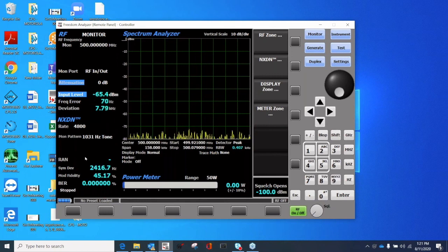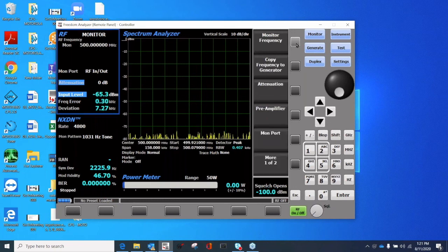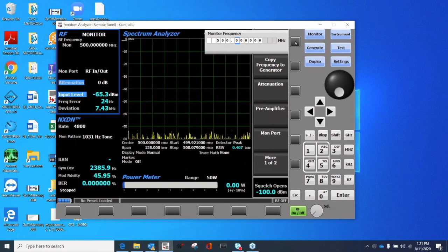Suppose you receive a radio from the field and want to do a quick test and see the health of this radio, if it has power, if the modulation is okay, if the vocoder is working and things like that. First of all, you should put the radio on the right frequency. You can go directly here to the monitor frequencies. For this case, I'm using here an ICF 1100 from Icom. It is programmed in VHF. Let me put the frequency I have at 149.190.